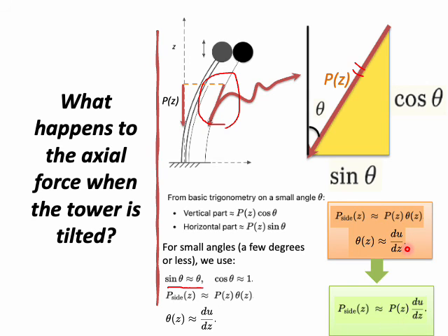I should emphasize that the sideways component is not just a detail. It actively pushes the tower further sideways. So even if the original wind load was what started the bending, the axial force itself is now helping to bend the tower more, or at least it can modulate the load-induced bending.